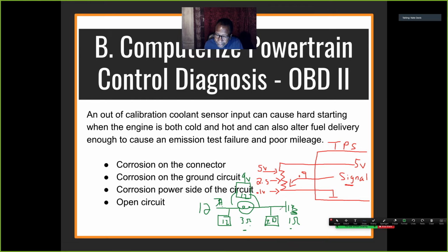Because now my ground side, instead of being 0.1 like on this side, it increased because I need this voltage to push the current through this resistor to ground. So that same analogy goes here in my head. If I got resistance here, my voltage here should go up because I need an increased voltage, just like I need an increased voltage here to push the amperage to the resistor that's over here. I don't know if that made sense or not, but this is how I figured that out.